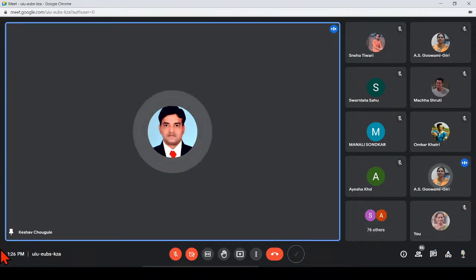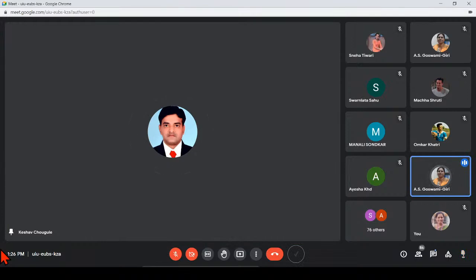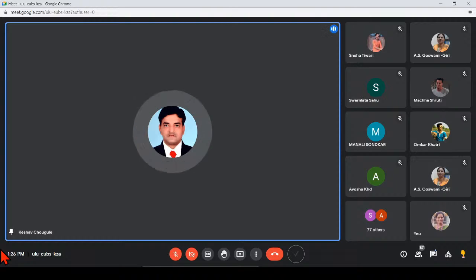One of the students, Almas, asked why sulfur dioxide is added to the juice. It is for purification. When sulfur dioxide is added, the juice is purified. It extracts the clear juice from the raw juice and removes the muds, as I showed. Mud is the byproduct of the sugar pit. It removes the mud and unwanted parts of the boiled juice. The main purpose of adding sulfur dioxide is clarification.